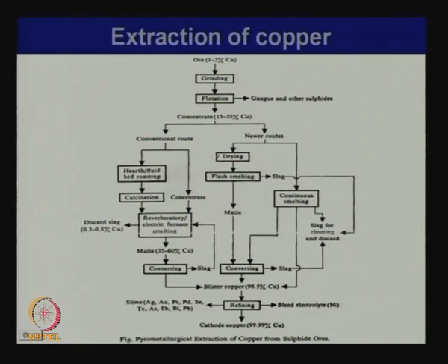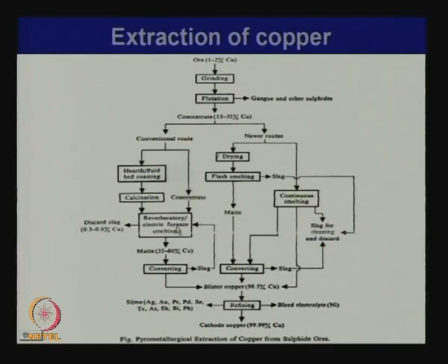So, all the oxygen has been eliminated from the system, and the slag that comes out, which has most of the iron slagged out, FeO with silica, limestone, quartz, etc. in a slag, it will also take out a small amount of copper, obviously that we cannot ensure. But basically oxygen is eliminated from the system, but what we get is a matte mixture of iron sulphide and copper sulphide.